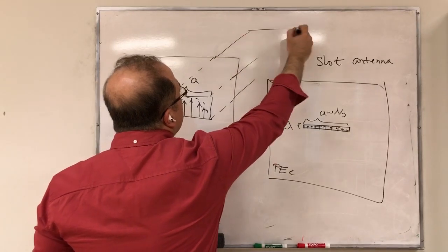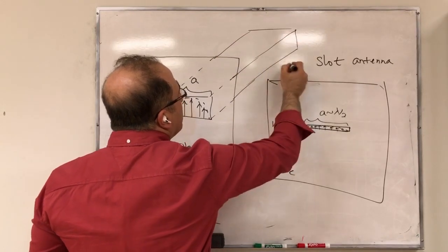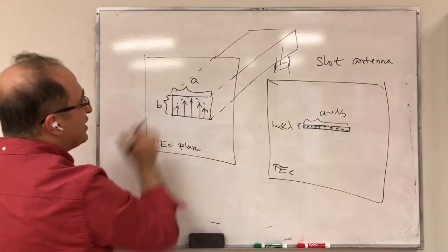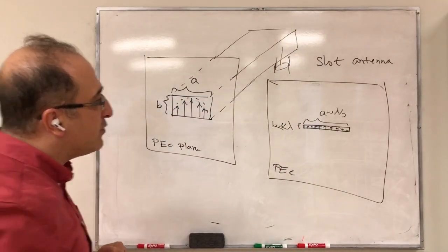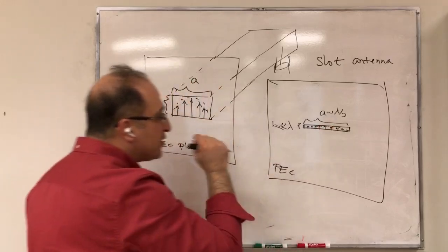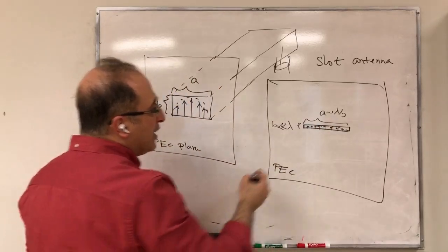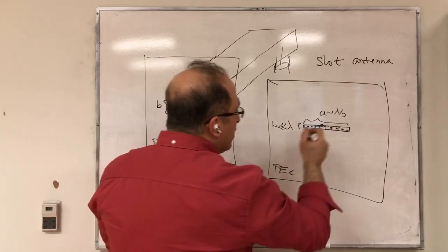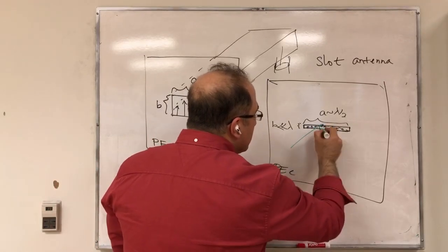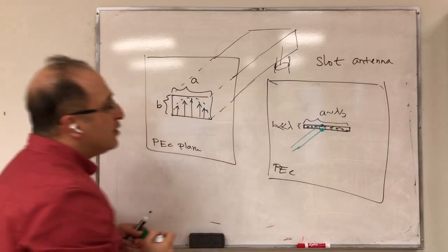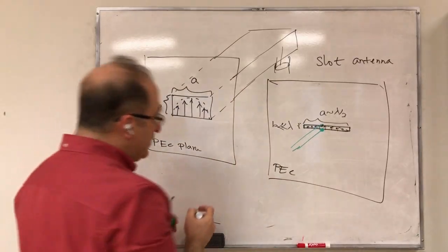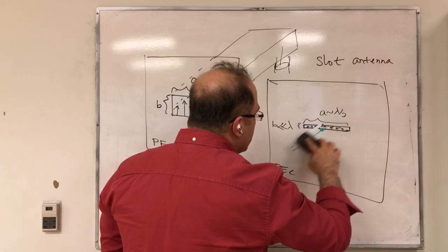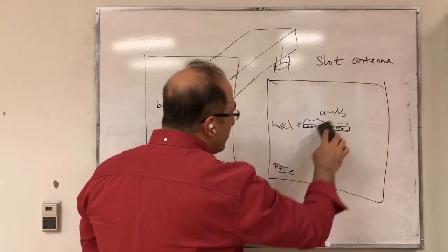So essentially we excite this waveguide, and this is the way that we get our electric field. In the case of just a slot in the metallic plane, perhaps you can use a 2-wire transmission line like this to bring the power to the slot, and then it can radiate for you. Or the other way you can do that perhaps is to use a coaxial cable.